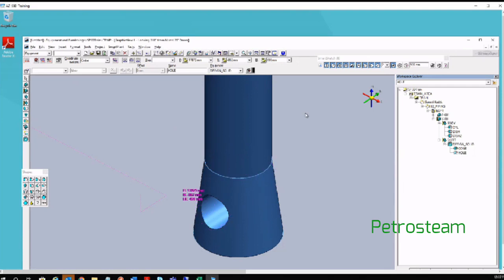Okay, this is how we will use negative shapes by creating design solids. One more type of property is available within the design solid, in the drop down. This is your positive, use it for this. This is your negative, use it for the cylinder. There is one more property, suppress the shape.